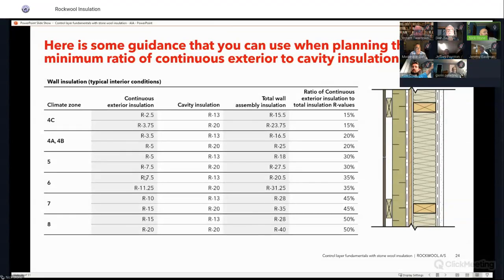But that's why these ratios really do play a critical role in these designs, especially as you move into zone 6. Well, that's even higher. That's even further away from the correct ratio to make sure you have no condensation. So having these exterior insulation packages that are not vapor open is definitely something to consider talking to builders about.